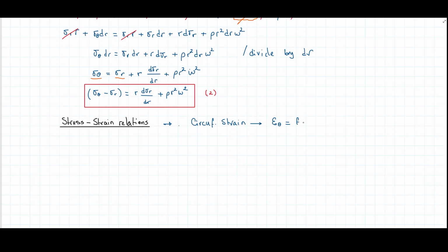Well, it's going to be the final circumference, the circumferential stretch, minus the initial value of the circumference, and then that's going to be divided by the initial one. So we can get the strains according to the original definition of what a strain is. So divided by the initial circumference. And then in the case of the radial strain,